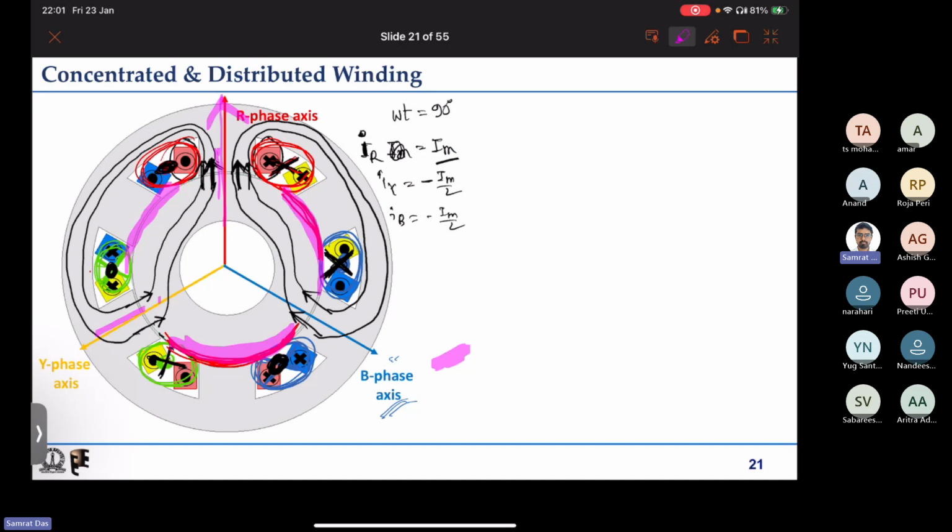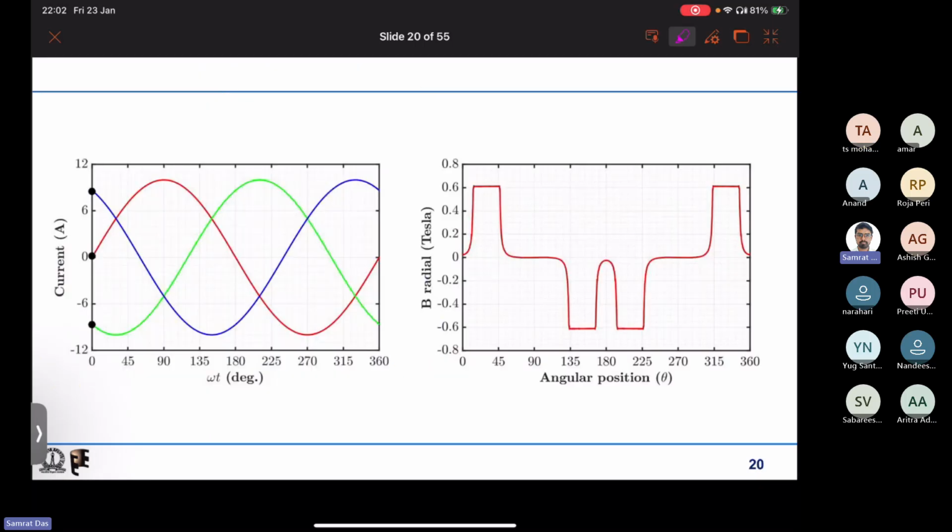If I plot this distribution, then we may eventually have even harmonics also along with odd harmonics, but the harmonic magnitudes will also increase. I have to plot the half-wave symmetry case and see. But without any doubt, the harmonic magnitude will increase. Is it good to have an odd harmonic or an even harmonic? Yeah, come again. Generally, for this type of distribution,